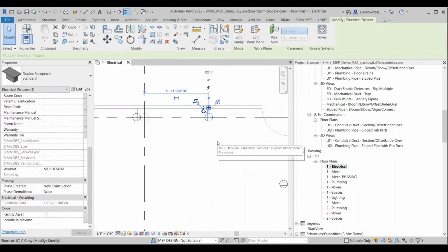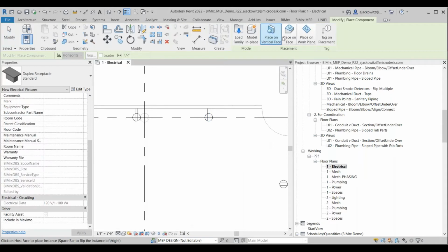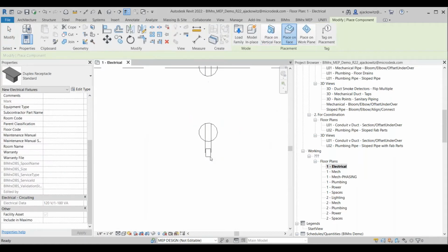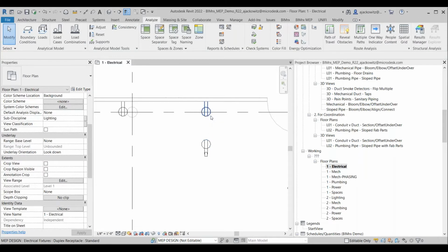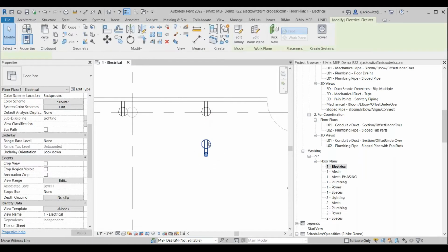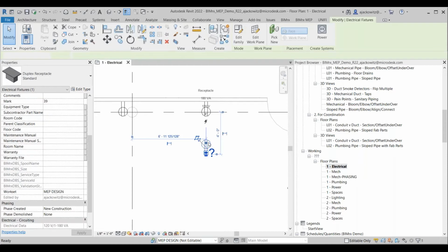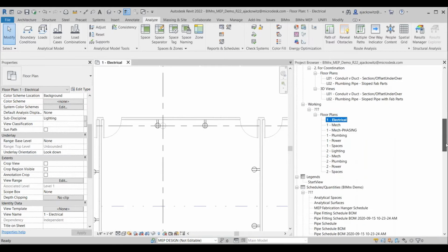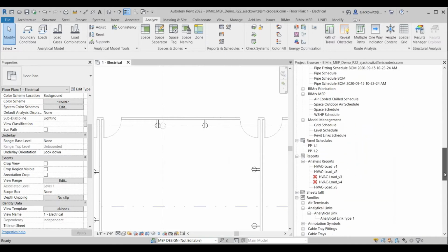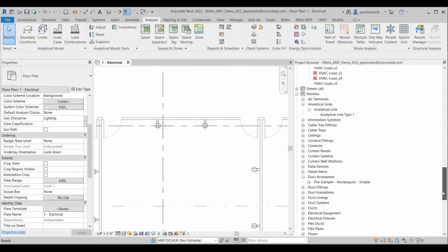If I were to just do a create similar here, place that on the floor, obviously I'd have to mess with some of the geometry here for visibility, but right, we're seeing that on now a wall face and a floor face. I'm sure most of you are familiar with that. That's now been added through for multiple categories. So we also have that now available for electrical equipment, generic models, lighting fixtures, mechanical equipment, plumbing fixtures, and specialty equipment.